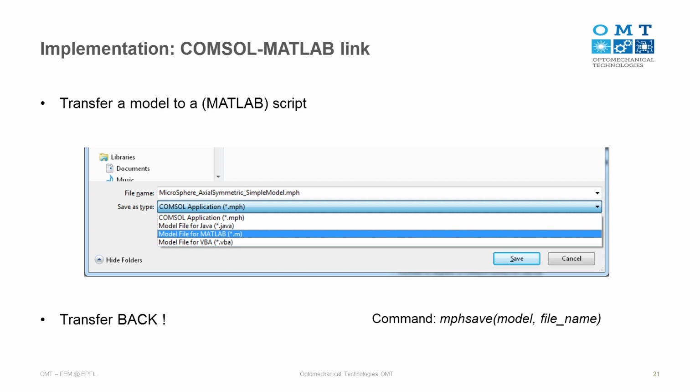So here is just using the COMSOL MATLAB link provided. I'm not sure if you have already heard of COMSOL MATLAB, at least in this workshop before. But here, a very basic transfer between MATLAB and COMSOL: you need to know what you have done in the software, and how it shows up in the MATLAB script. So one side is to transfer a model to a script. To do this, it's pretty easy. You save your model as a script.